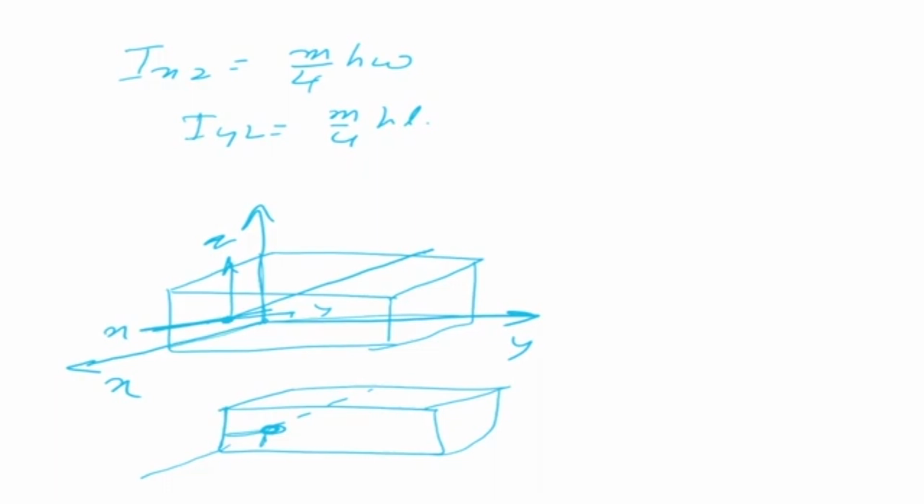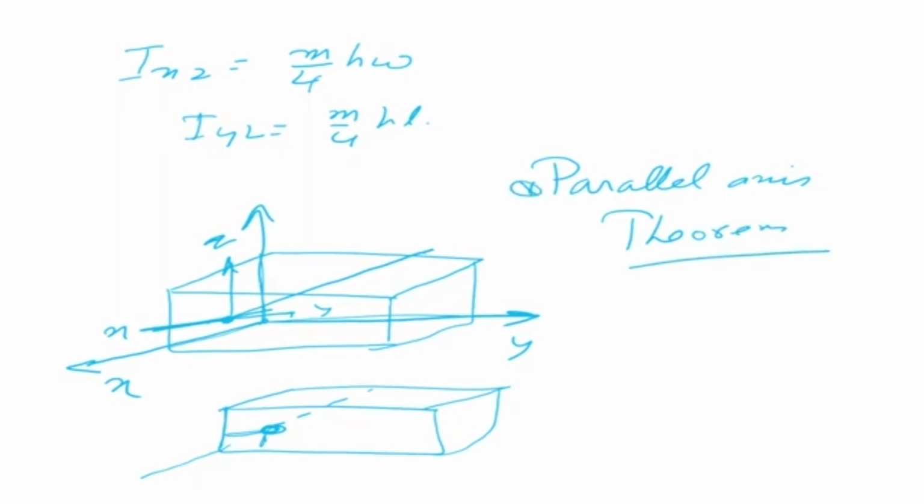So for that, we can use the parallel axis theorem, in case the axis is shifted. By using the parallel axis theorem, Izz, for example, is equal to Izz plus m into xc squared plus yc squared. So we can simply use the parallel axis theorem, and for cases where, in this particular case, the axis is passing through the centroid, xc and yc, I put it like this.